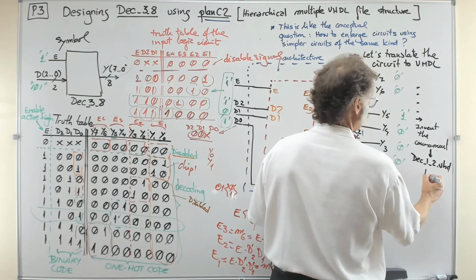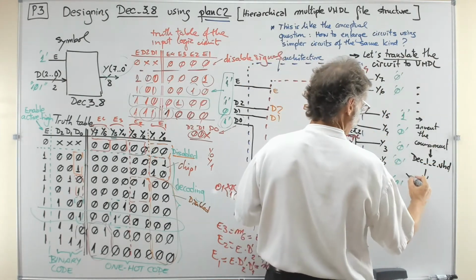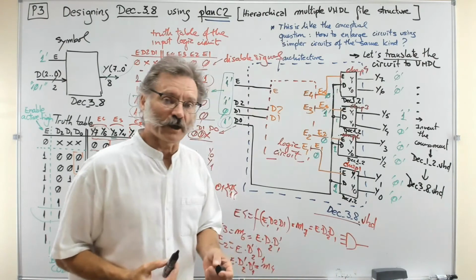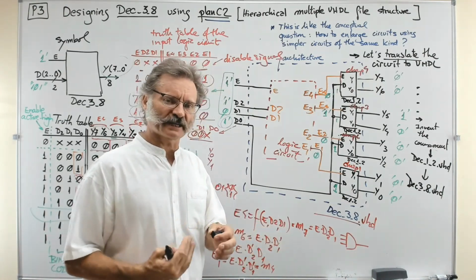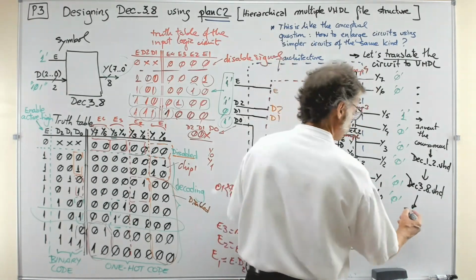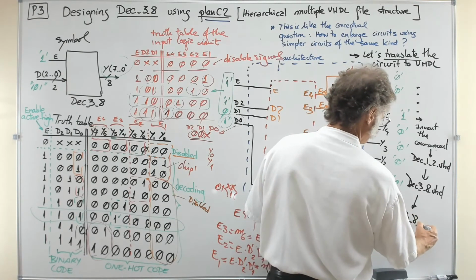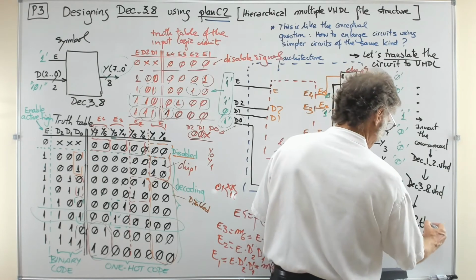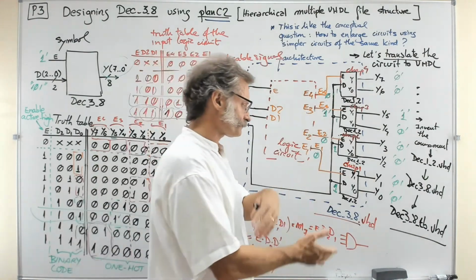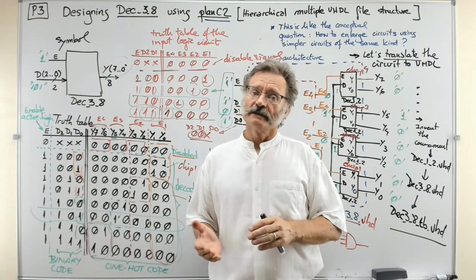Once you have the component decoder12.vhd, you will need to generate this translation of the decoder328.vhd, and then what you have to do is just generate a skeleton of a template and a skeleton of a test bench. So you will need later on the decoder328_testbench.vhd. So you will translate at this stage another